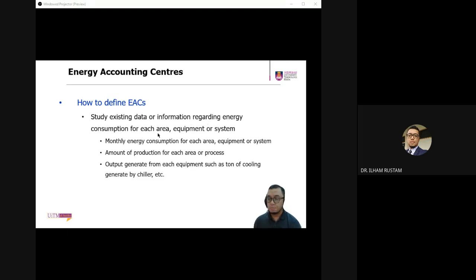And then basically data in regards to the energy consumption for the area, where of course you need to have some sort of understanding. You can't tap every meter line, it would be expensive, the data logger that you want to measure with, you have to buy it. If possible, tap at the main source before it enters that area.